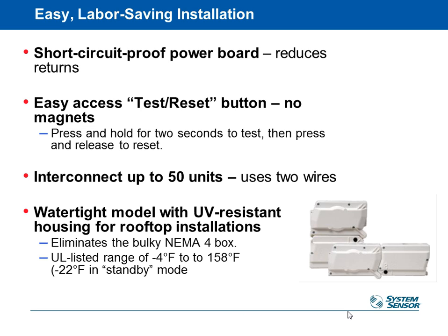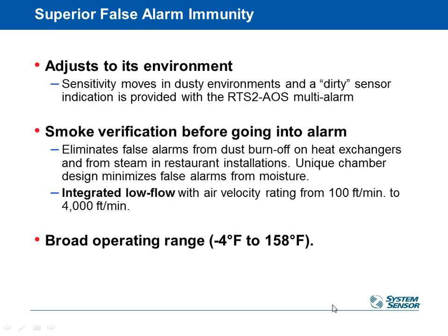They have all the test functions built into them. You can connect up to 50 of these units together with a pair of wires, so that way they're interconnected, so any one of them could alert the others. There is a weather-resistant version available for outdoor use if you have ductwork outside, and that's the only place to put it. It's NEMA 4 rated.